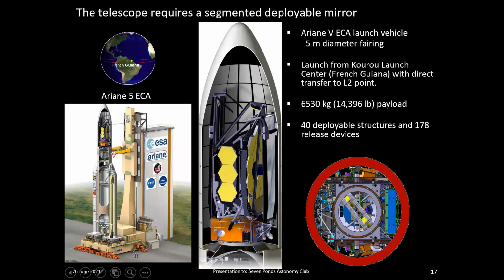So we really have 18 telescopes. And these mirror segments are mechanized in 7 degrees of freedom, the 6 you're familiar with, plus radius of curvature, so that they can all be finely adjusted so that they play together as if they were one big mirror.